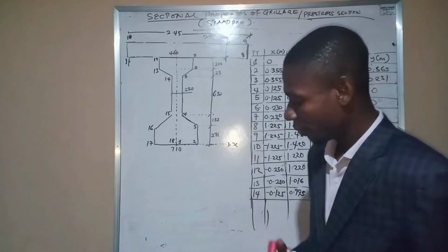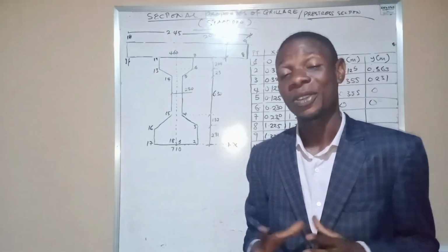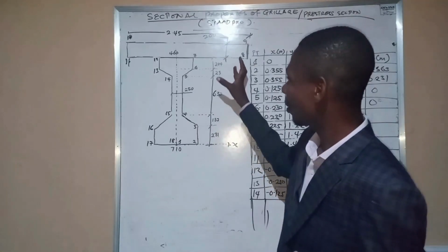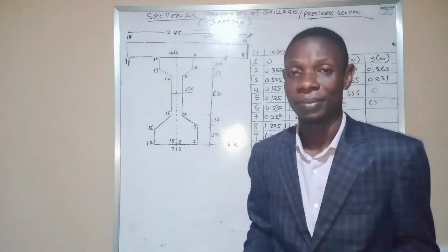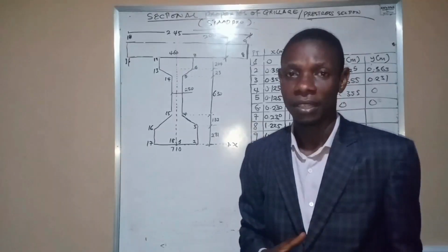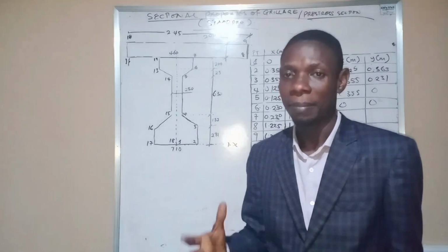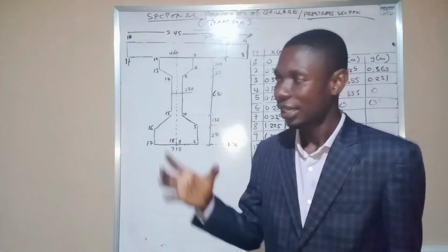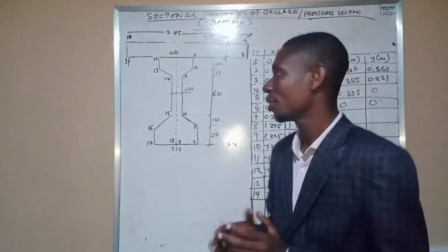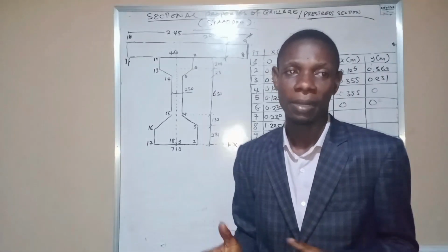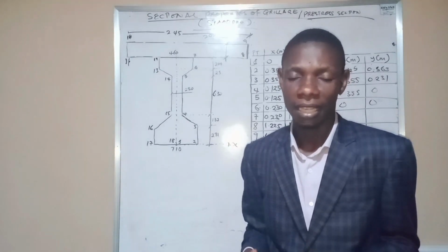All right. So, apart from this section, we also have the crossbeam. If we have the crossbeam, the same method that we use in calculating this section and inputting it in our STAAD.Pro file can be used also to determine the properties of the crossbeam, or the diaphragm. Once we do that, we can apply it to our grillage, the diaphragm, and this longitudinal section. So once we have the transverse and the longitudinal section, we can apply our grillage, apply necessary loadings, and obtain the bending moment and shear force diagram and expression.